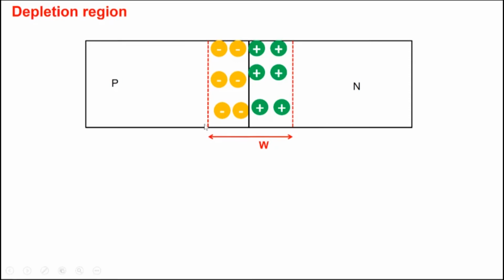But if you're wondering how large the depletion width is, we can give you an expression for it. Again, everything at equilibrium. So the depletion width can be written as the square root of 2 times the permittivity of silicon, since we are talking about a silicon p-n junction, Q of course, Na, the doping of acceptor atoms, Nd, the doping of donor atoms, and the built-in voltage here. And for the built-in voltage, we've already given an expression.